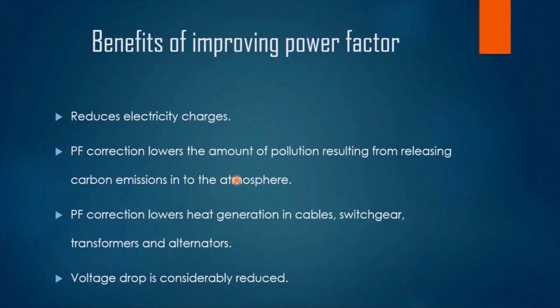Now, let's see what the advantages of improving a power factor are. First, it reduces electricity charges. Second, it lowers the amount of pollution resulting from releasing carbon emissions to the atmosphere. Third, it lowers heat generation in cables, switchgear, transformers, and alternators. And finally, voltage drop is reduced with a better or corrected power factor.